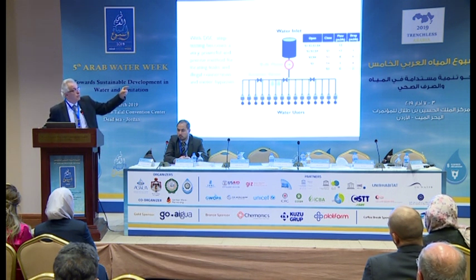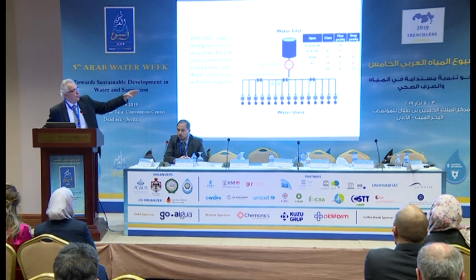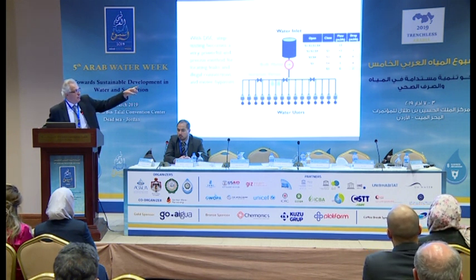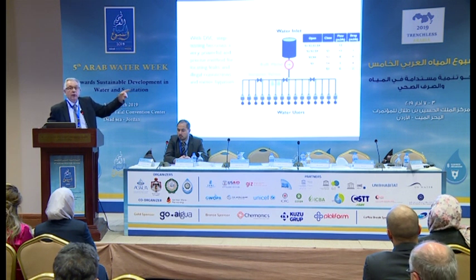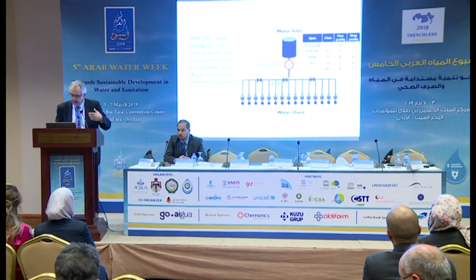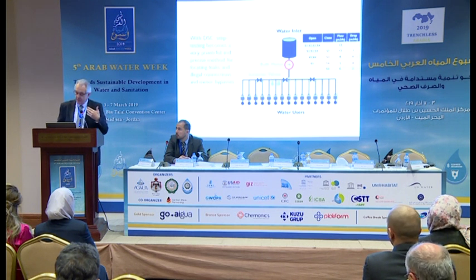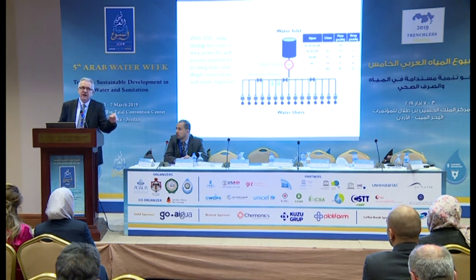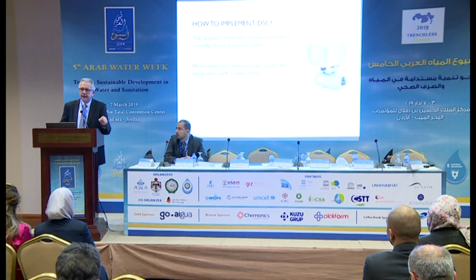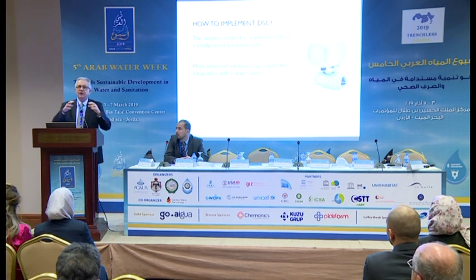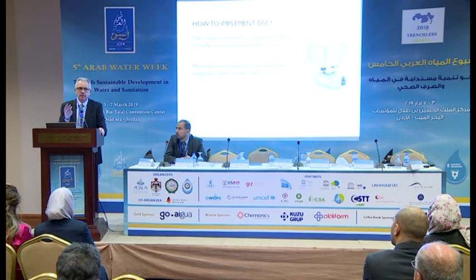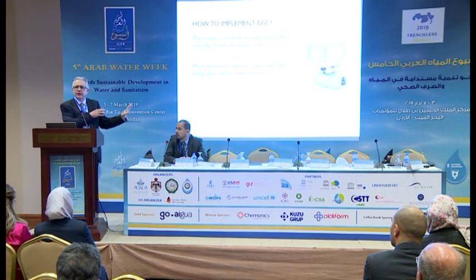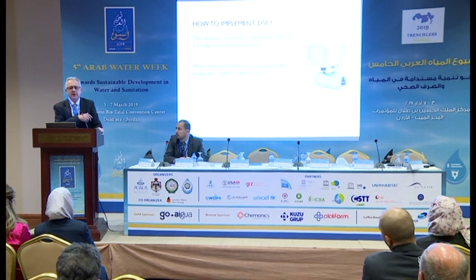So we can see and prioritize. In this particular example, step 2 and step 3 are the ones that we should be looking at with priority over step number 1. So we can go with step testing and find the leaks in the network that we cannot find under intermittent water supply. Now, I've just highlighted very briefly the benefits of having downstream control without doing anything out of the ordinary. All these things we do when we have continuous supply, or some of them we may be doing under intermittent water supply.